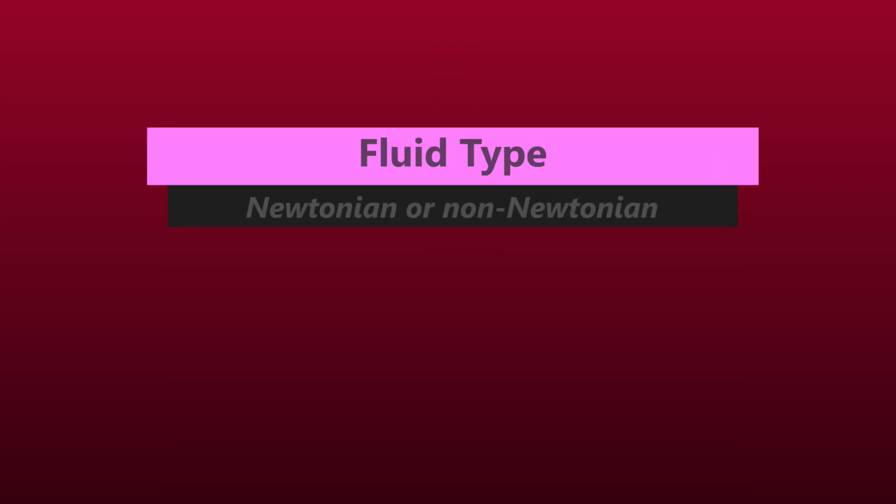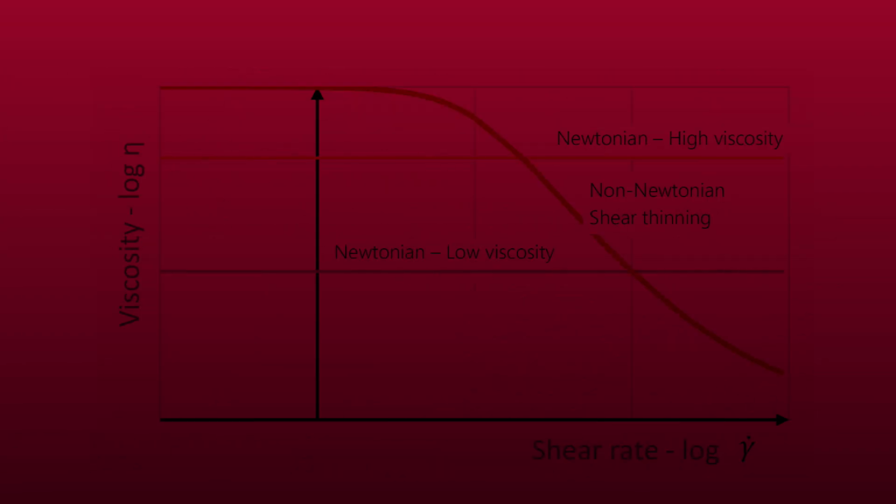The behavior of a hydraulic system depends heavily on the type of fluid being used. Fluids are broadly classified as Newtonian or non-Newtonian. Newtonian fluids, such as water or light oils, maintain a constant viscosity regardless of shear rate. The relationship between shear stress and shear rate is linear and predictable. However, many industrial and drilling fluids are non-Newtonian, meaning their viscosity changes with shear rate. This makes their behavior more complex and requires specialized rheological models to accurately predict pressure losses and flow performance.